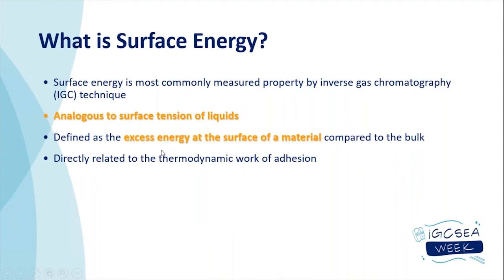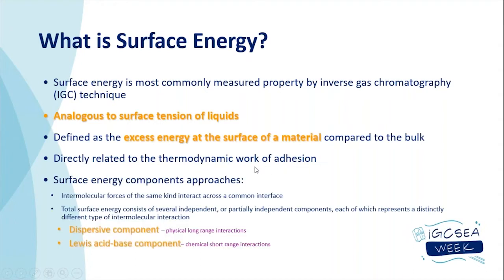What is important is that it is directly related to the thermodynamic work of adhesion. So anything where you have interfacial interactions between two powders, a powder and a liquid, a powder and a vapor, any solid materials, the initial interactions will be driven by the surface properties of the different materials.